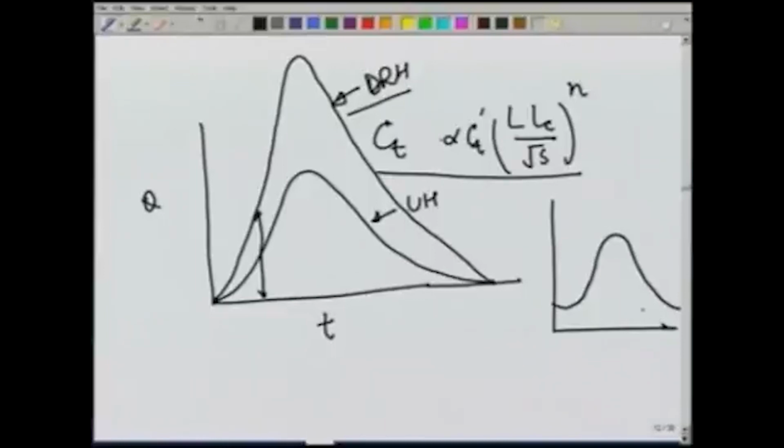Our aim of developing this total runoff hydrograph is to be able to answer questions like what is the maximum flow in the stream, what is the minimum flow in the stream, what will be the total amount of water which passes the stream for a fixed period of time, or there could be a lot of other questions like one question which typically people ask is what is the reliability of a certain discharge. For example, let us say 85% of the time, we say what is the discharge which we can assure will be available to us 85% of the time. So, to answer all these questions, we would look at alternative ways of presenting the same information.